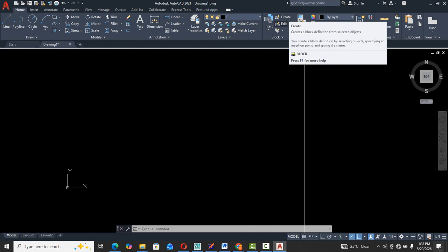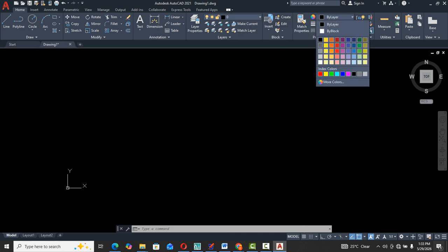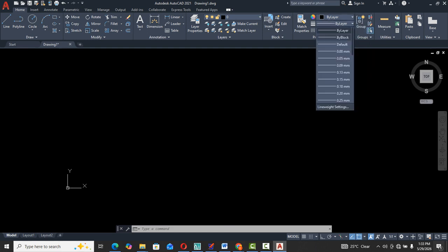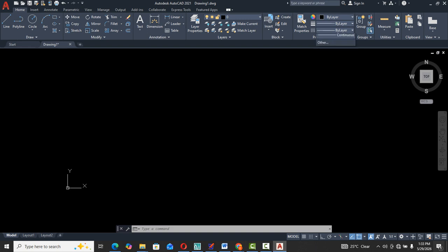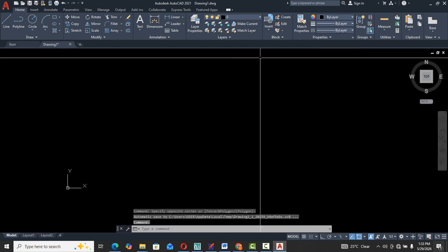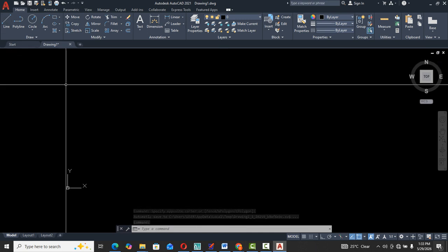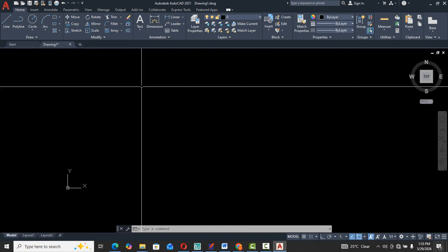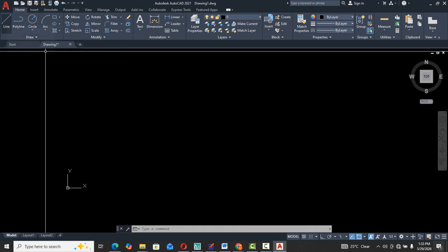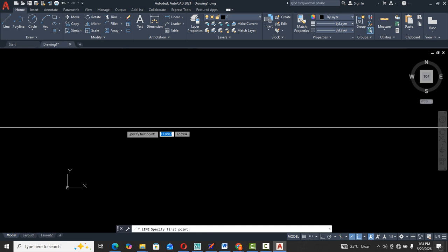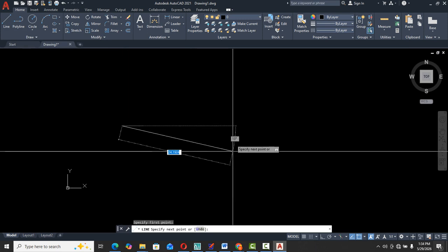If you go to trim, you see that you have trim and extend. So trim is to shorten. If you look at it, you see that it has a brief description of what it is. To trim objects is to meet the edges of other objects. To trim objects, select the boundaries, then press enter and select the objects that you want to trim. To use all objects as boundaries, press enter at the first select object prompt.